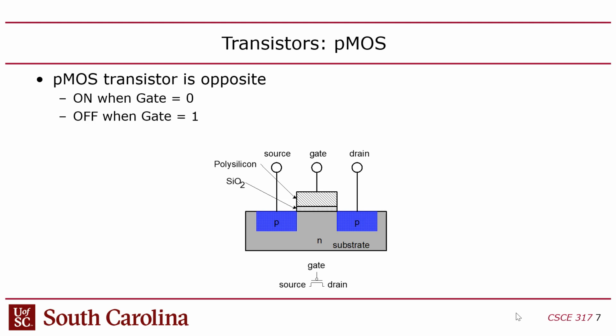So you have negative voltage here to get positive charge carriers down here on the other side of the capacitor plate. You guys with me? So it's not really that when you put a 0 in to turn on a PMOS, you're just putting 0 in. You're actually putting a negative voltage that exceeds the threshold voltage in terms of its magnitude. So the threshold voltage here will be like negative 700 millivolts.